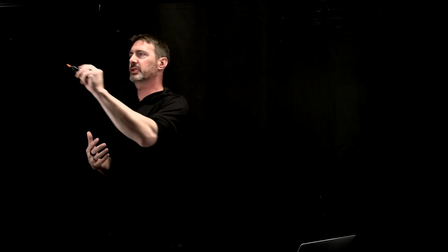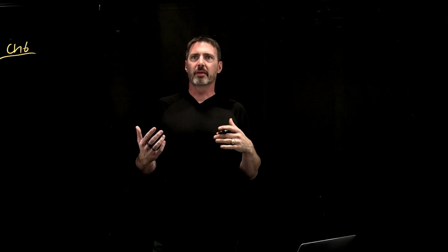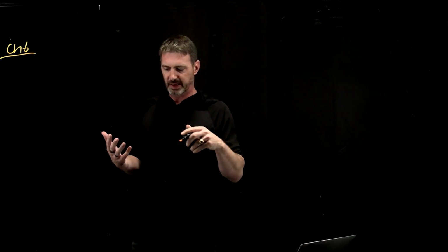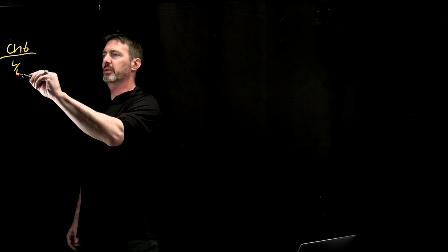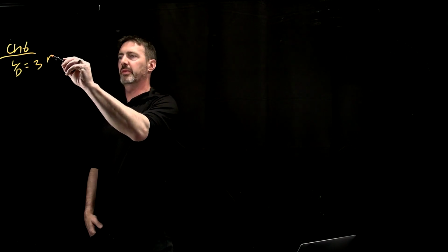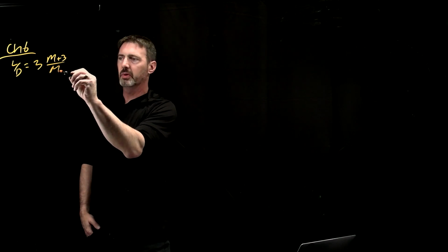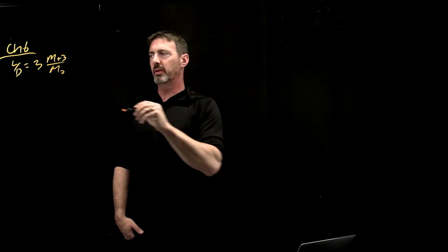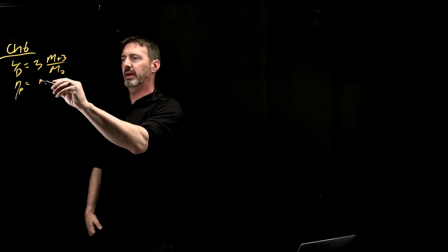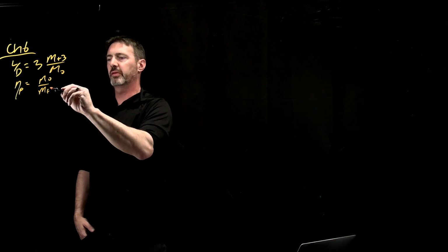And so the first section, in chapter 6, the first one of note is there's a little bit where Kuchemann derives and looks at some equations and says, hey, this is why there's a good reason for the model to be L over D is 3 times Mach number plus 3 over Mach number. And then he also showed that the propulsive coefficient went as Mach over Mach plus 3.